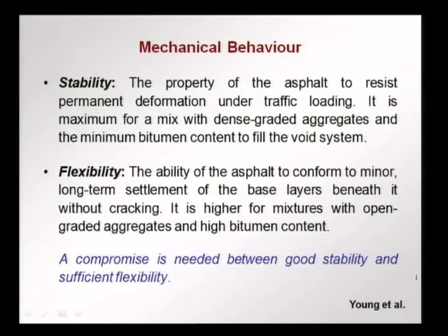Now, you can clearly understand that stability and flexibility are competing aspects. We have to have a good compromise between stability and flexibility. We always need good flexibility, but we always want good stability with a sufficient amount of flexibility. That way we will have a surface that does not become undulating with time, can take traffic as it should without bumpiness and roughness and disturbance to the comfort while driving, as well as not have cracks whenever there is a small settlement of the base layers.